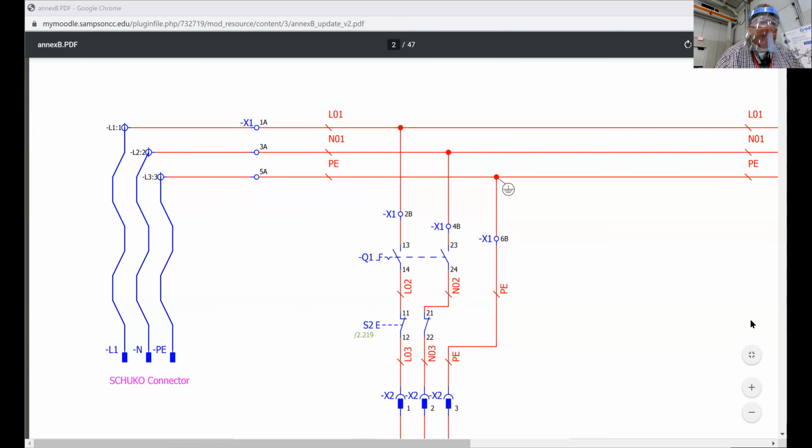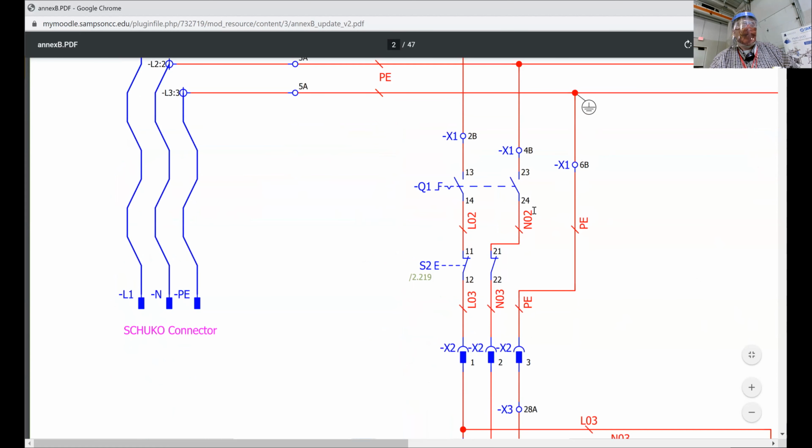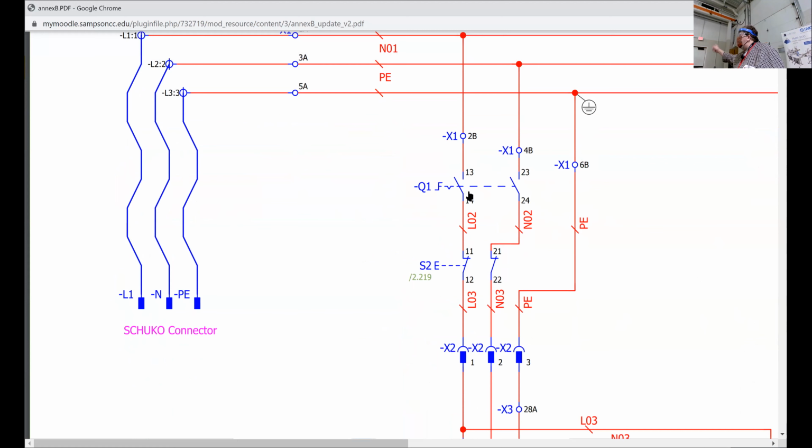Again, we're going to look at how we know that this is a switch, and how we know the difference between a switch and a push button. You see that V in there? The V represents a locking detent on a switch. This is an international IEC symbol that's used if the machines come from Spain, Germany, Italy, anywhere other than the U.S., that come from Japan, South America, Canada. Everybody in the world is using IEC symbols. Schindler, you're using these symbols. These are the same symbol sets that Schindler uses because they're a European company.